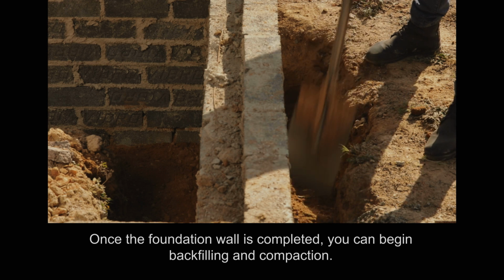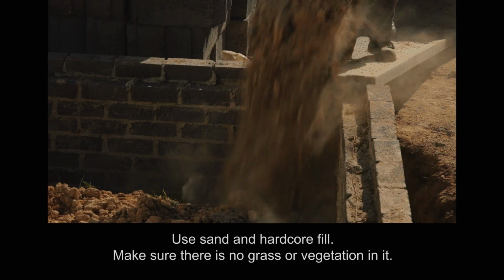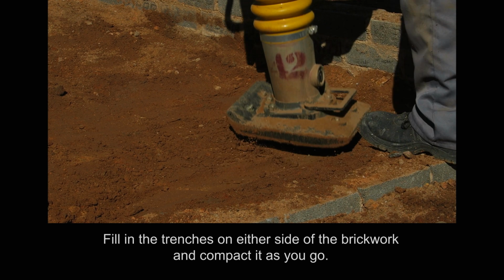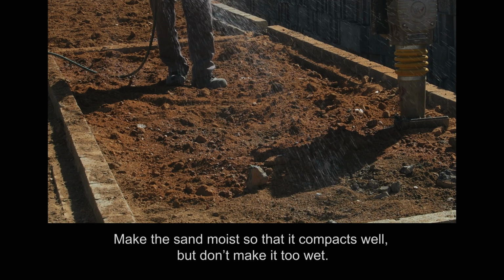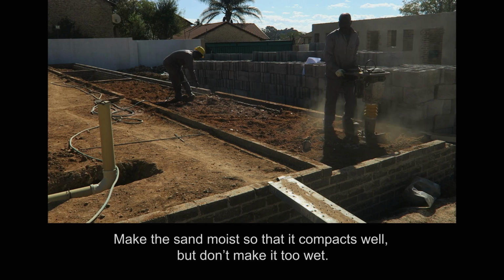Once the foundation wall is completed, you can begin backfilling and compaction. Use sand and hardcore fill. Make sure there is no grass or vegetation in it. Fill in the trenches on either side of the brickwork and compact it as you go. Make the sand moist so that it compacts well, but don't make it too wet.